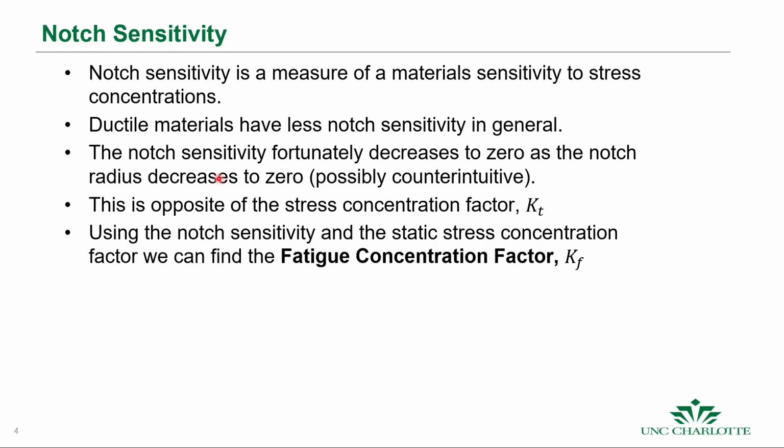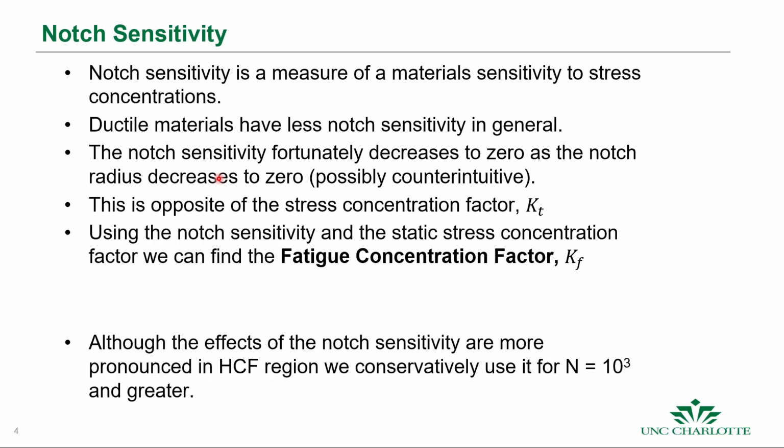And the way we modify it is through that notch sensitivity. The effects of the notch sensitivity are more pronounced in the high cycle fatigue region, but we use it conservatively for 10 to the 3 and greater cycles.